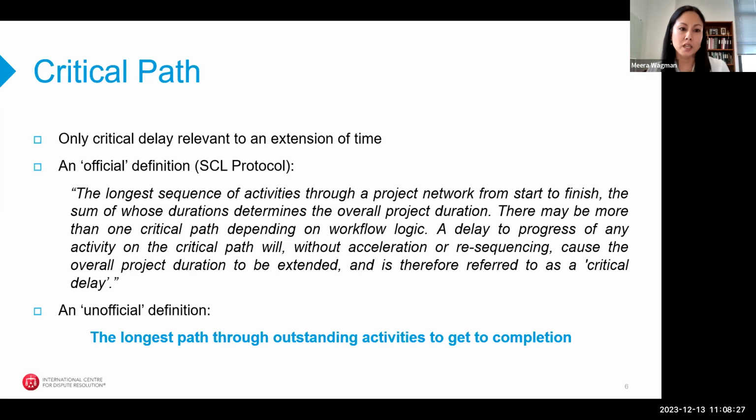And you have, in the beginning of a job, typically a baseline schedule that will have your as-planned critical path. That's how the project is envisioned to be executed, and what sequence of activities is driving that completion date. As you move through the project execution, that critical path in subsequent schedule updates, as progress is being achieved or not being achieved, can change. In complex projects especially, you rarely see the critical path staying as it was in the plan. It evolves over time and changes and shifts in reaction to delays and impacts that are experienced on the project.